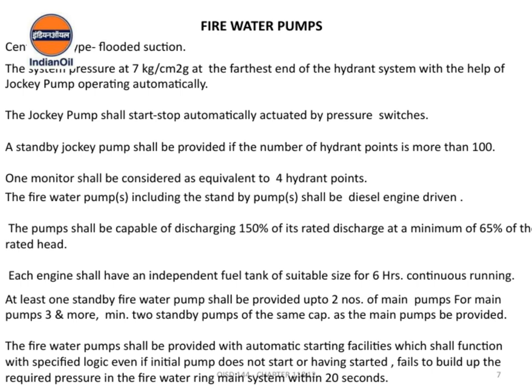Remember, for capacity calculations, one monitor is considered equivalent to 4 hydrant points. Finally, these fire water pumps are of the centrifugal type with flooded suction, which is ideal for ensuring efficient and reliable operation in emergency scenarios. This comprehensive setup ensures a robust and reliable fire water system, vital for safety and compliance.